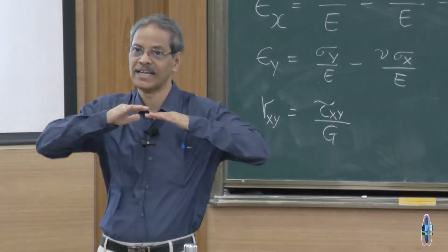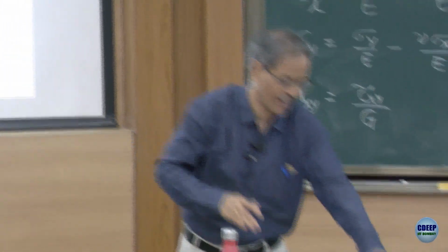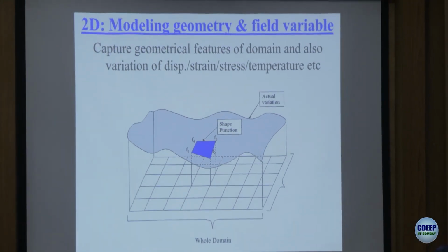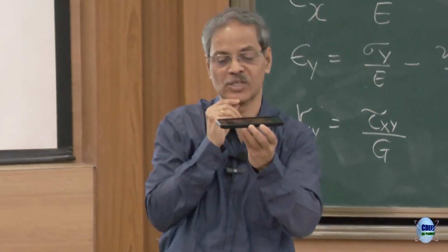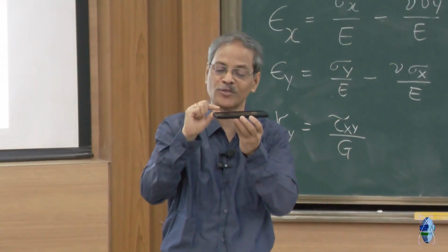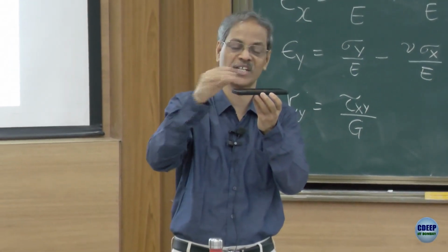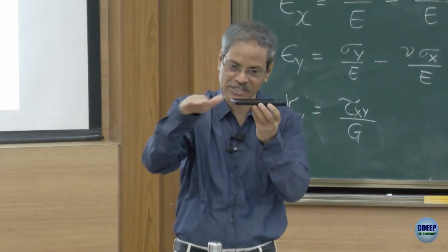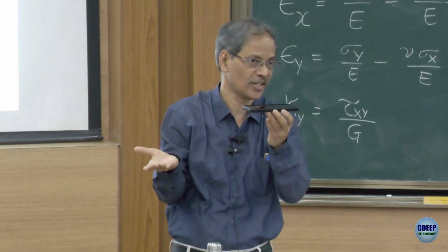So if you extend this logic, there is a two-dimensional domain, like for example this. Length is there, breadth is there, they are comparable in dimensions, thickness is small, so I have assumed that temperature or velocity or stress don't vary in the thickness. So I have reduced the problem to two dimension, but in these two directions I cannot make any intelligent guess or assumption.